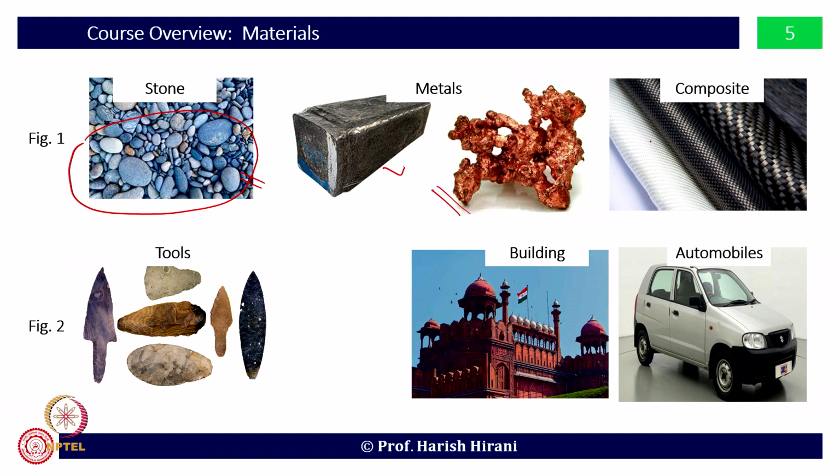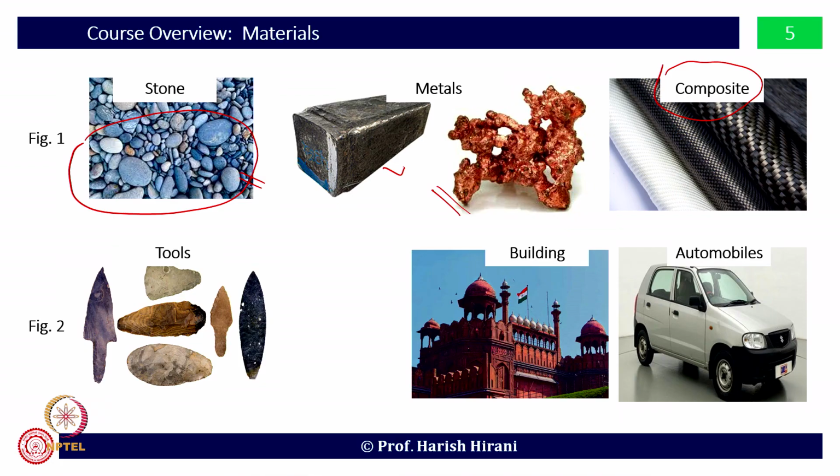Even composites are a very good solution as such, but we know that fragmentation or delamination happens very frequently in composites. And they are very susceptible to UV radiation. In the presence of radiation, the lamella may also break into smaller pieces, and that causes a major problem. If the fibers are broken, naturally the composite material will lose its strength. Another thing is that if they are made layer by layer and delamination occurs, naturally that will also be problematic. So, we need to understand those things.